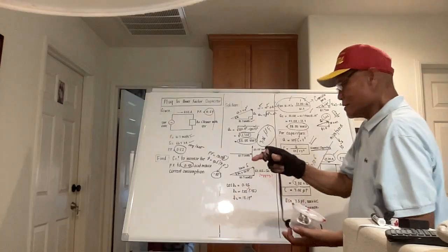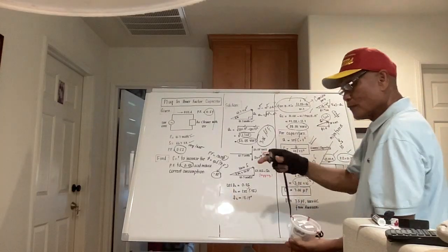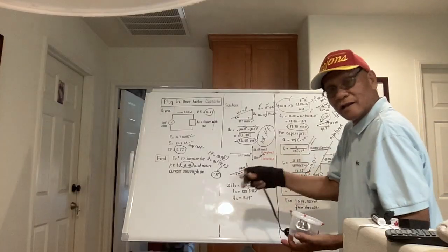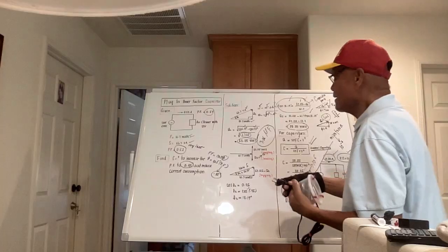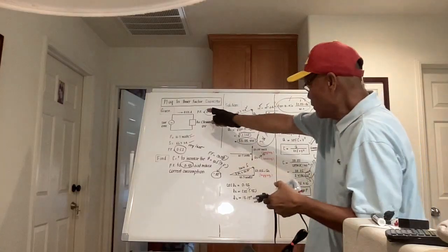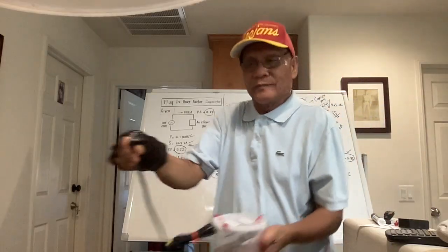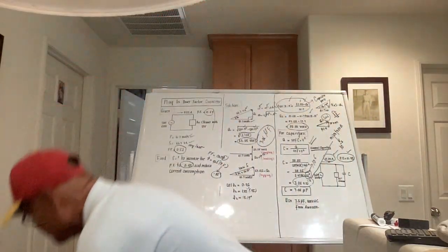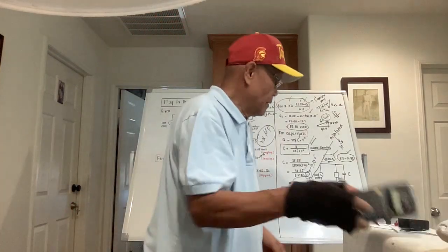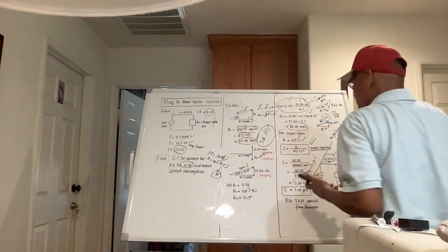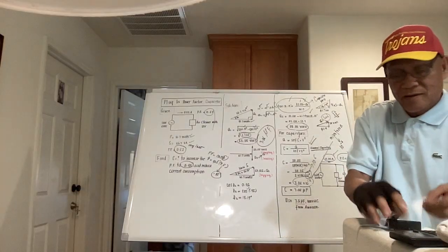And what comes out is, by using 7.5, the power factor of my air cleaner now is 0.92, and the current decreased from 0.55. Actually, the current will be lesser, okay?